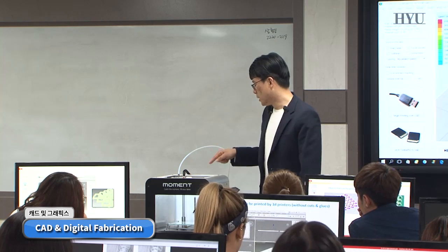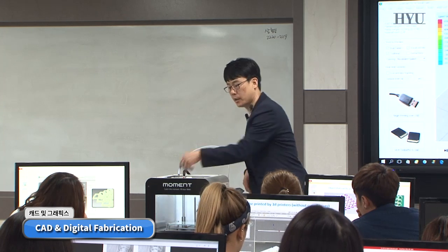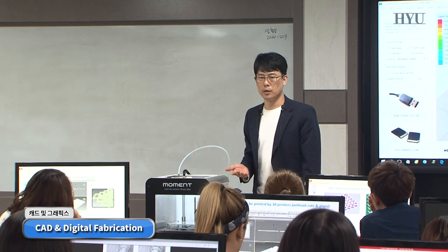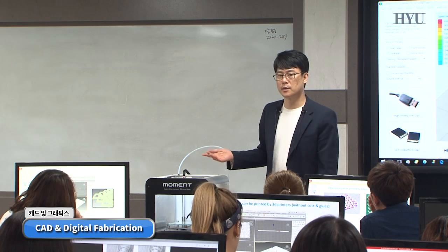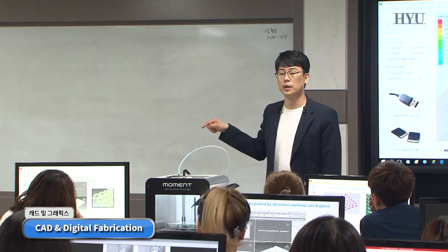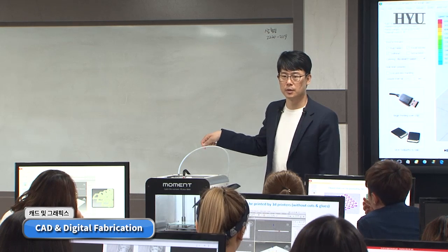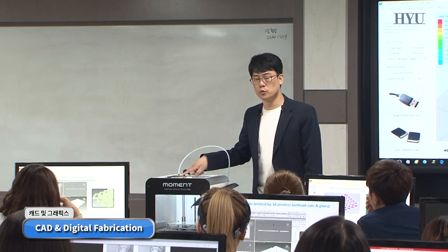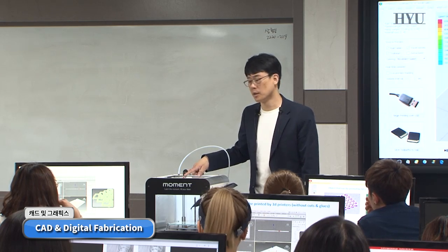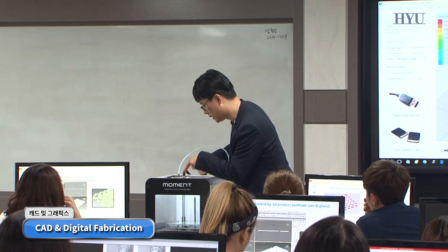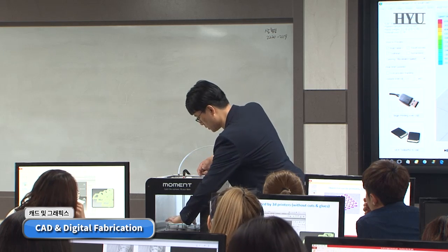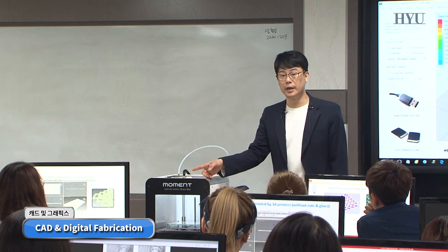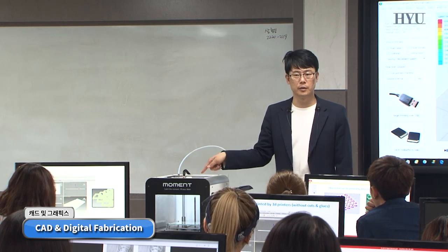Okay, start. So the printing bed and the nozzle are going to be heated, okay, to 170 or around 200 degrees Celsius, very hot. So you should be very careful, okay, very hot. Anyway, the nozzle, after heating, bed means this one, okay. After that, this one is moving. What I need to do is click print, that's it.